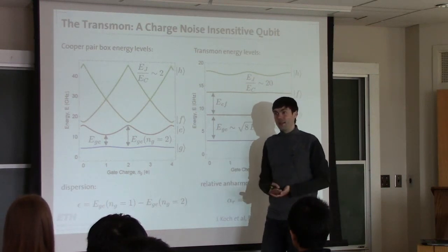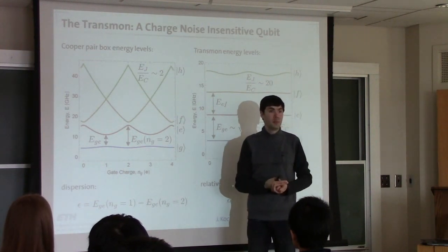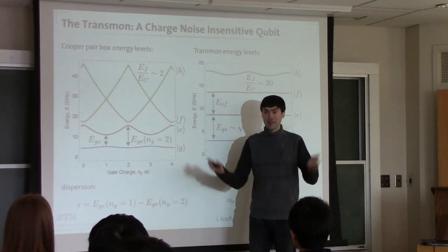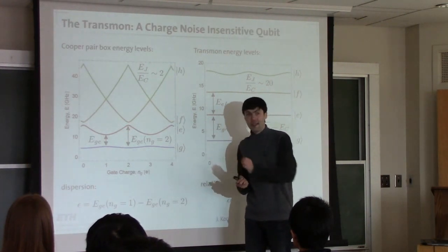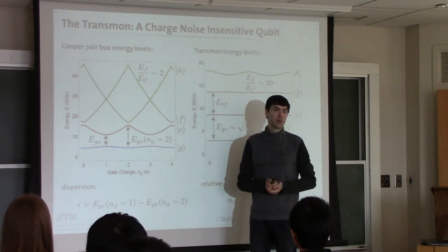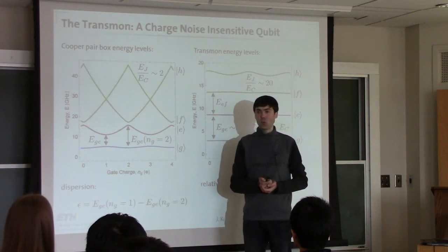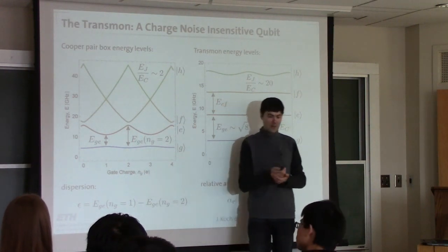So in the end, the summary of the lecture is that all we needed to do to create the best, the most robust qubit is to take a classical circuit, make it slightly nonlinear, and that is called a transmon. Transmon is the best superconducting qubit to date. And here I stop, and next lecture we continue with transmon experiments.